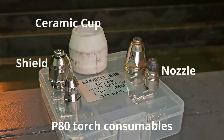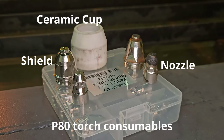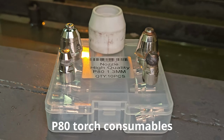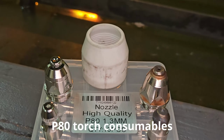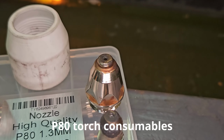To pierce or cut the material, you need a specific arc power. A weak arc will not be able to pierce the base material, but it doesn't mean the more powerful arc is better. Too much power will cause the material to overheat, generate more dross and a bigger kerf, the width of cut.